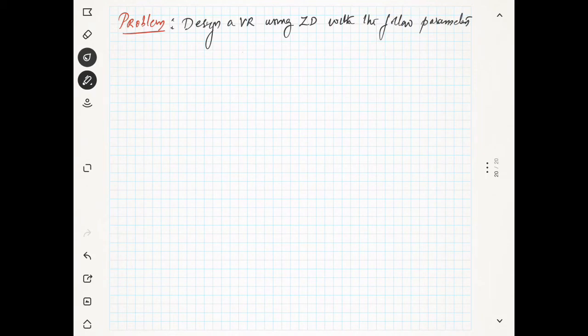It is given that your Vz is 15 volt. The minimum current required for the Zener diode to turn on, known as IZK, is 0.25 milliampere. Then PD max is given, PD max is equal to 1 watt.